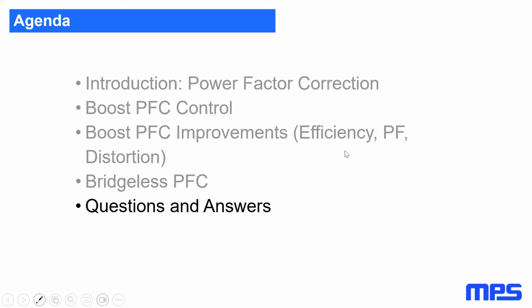So of course, this makes it more complex and costly. Now, if you compare it to a synchronous boost, then there will also be a high side MOSFET, so in that case there will also be one high side drive. But practically, usually the controller for totem pole will be a little bit more complex because it needs to drive 4 MOSFETs. But again, it will bring you some advantages and some results that you cannot reach with the other one.